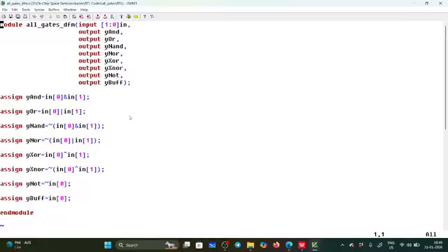Okay, the compiler will take it here. Here I declared the input and output. I have not declared them with any data type. By default, it will take the net data type, and that too, the wire data type it will take. Understood? Okay.